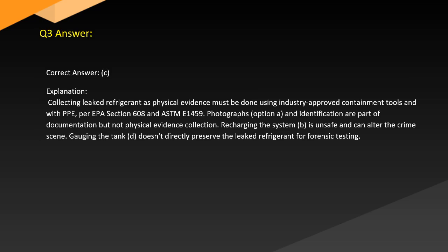Answer. Correct answer: C. Explanation. Collecting leaked refrigerant as physical evidence must be done using industry-approved containment tools and with PPE per EPA Section 608. Photographs and identification, option A, are part of documentation but not physical evidence collection. Recharging the system, option B, is unsafe and can alter the crime scene. Gauging the tank, option D, doesn't directly preserve the leaked refrigerant for forensic testing.